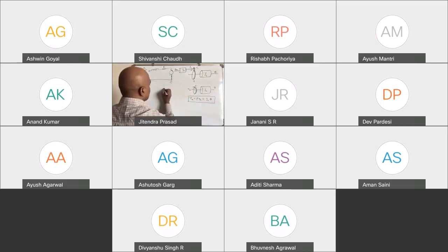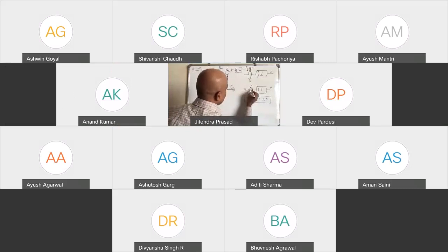So this will have Jm here, and then the rotation is theta m, and then we have another torque, the gear here, and that gear has radius R1, but the force is the same, right? And the force will be in the opposite direction. So let us say, looking from this side, if this motor is driving it anti-clockwise, there will be a reaction, because this is a load for this one.